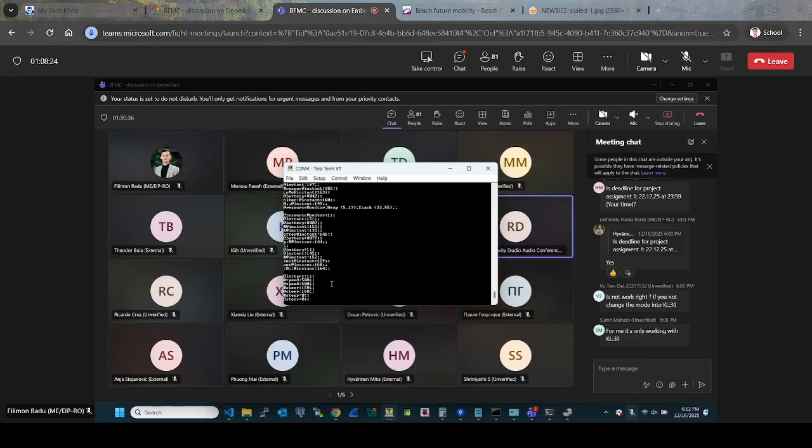And also we have a few commands, the velocity control duration command. So type hashtag VCD, double dot, the speeding value, 150, and the steering value 10 degrees for the next 2 seconds, let's say 20.